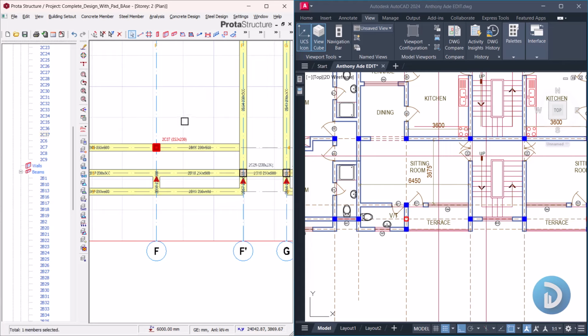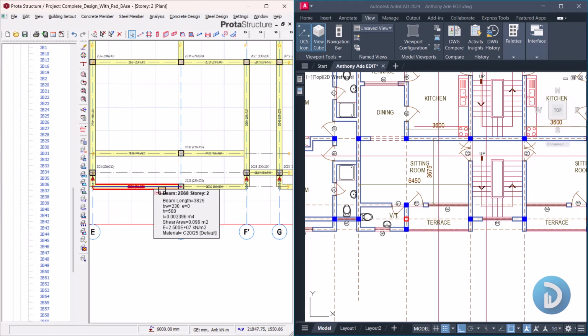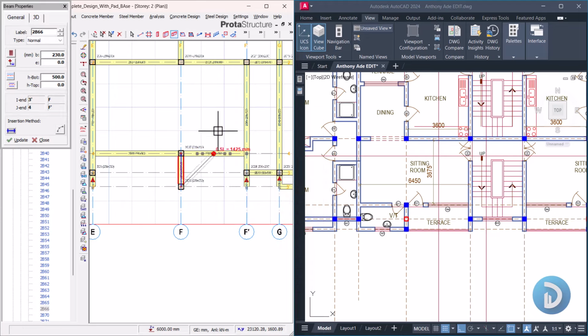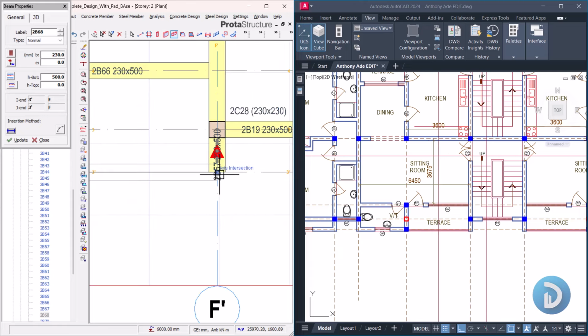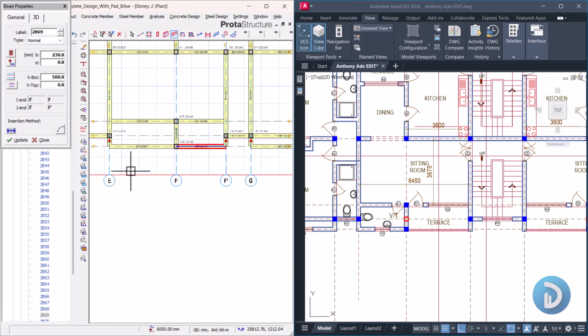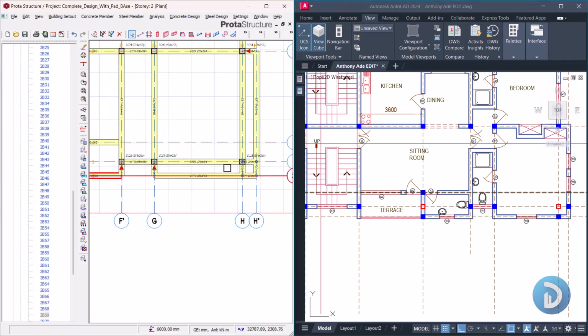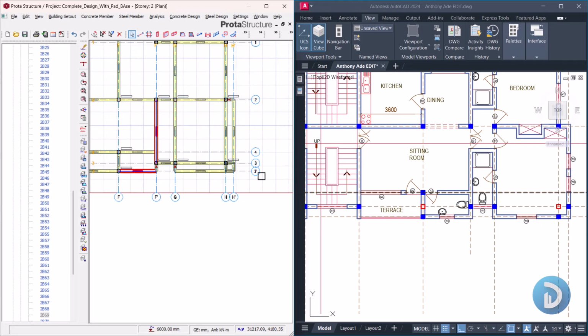We'll take this out, right click, properties, reintroduce this here, take out this beam, take out this beam as well, can take this out, and we can redraw. Okay, so let's draw this here, then we can cantilever from here to this short part, and let this also rest on this short part. Okay, so let's close this. Then we have our flush here, which is okay, and the same modification we made to this part is what we'll be making to this other right hand side.